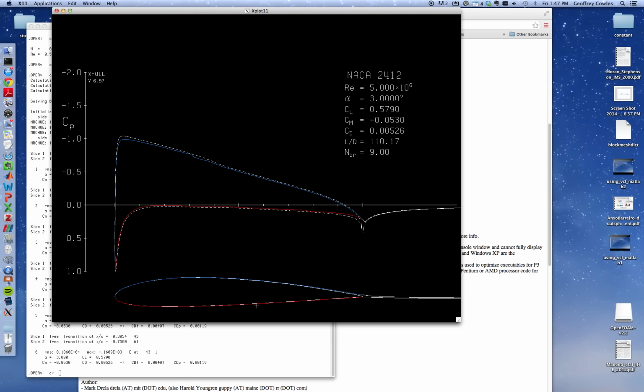And then we have some deceleration starting here, even on the upper surface. The pressure gradient is adverse, and it's decelerating all the way to the trailing edge. And on the lower surface, it's decelerating from about here. The pressure coefficients are getting more positive here until we match the pressure condition at the trailing edge. And you can see the differences that occur, particularly at the trailing edge, because you have a small wake here. It's hard to predict that, but there's a small wake here.